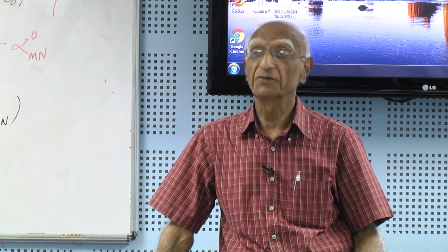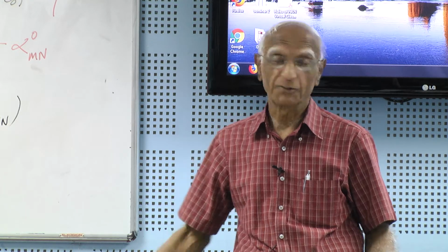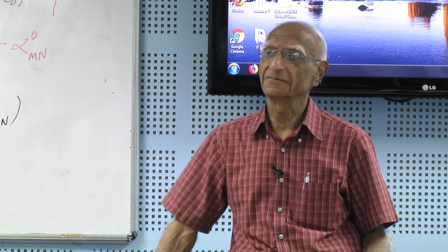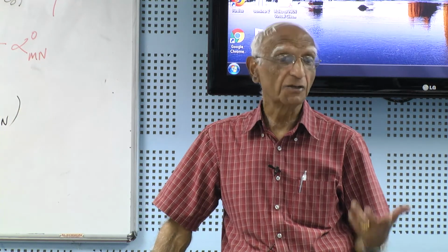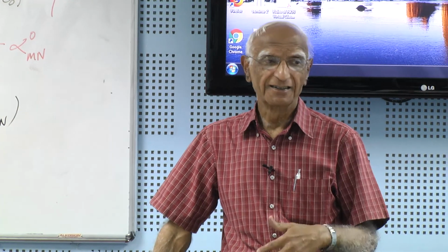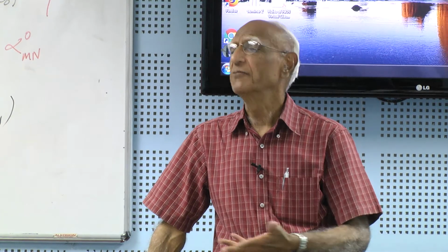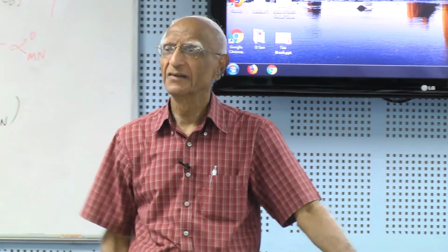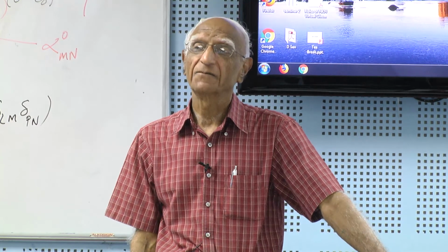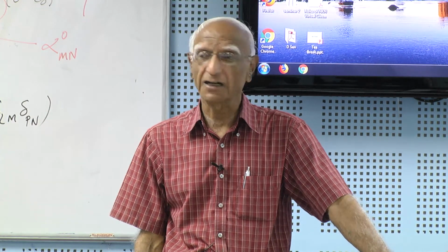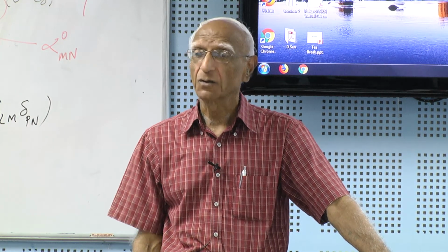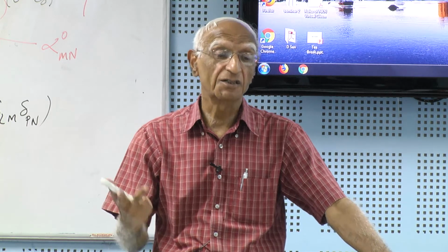See, we have to figure out experiments that will give us these 21 constants. I can tell you for 2 or 3 or something like that, or maybe 6. If I do orthotropic material, then there are 9. If we do transversely isotropic, there are 5. If you do isotropic, there are only 2.